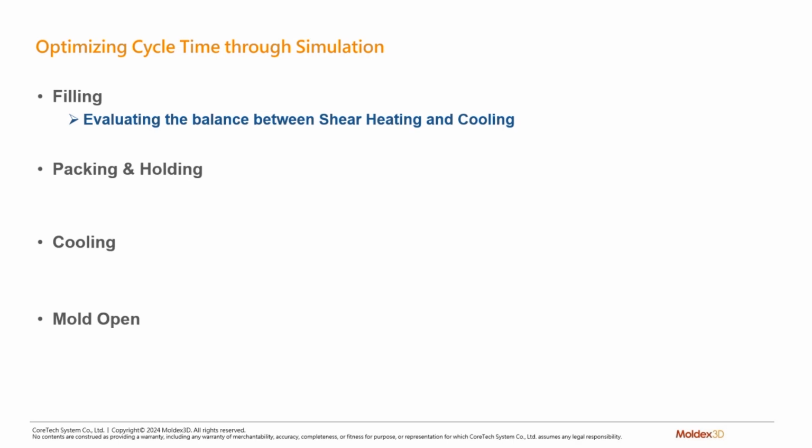So filling, how do we go? We will look at balancing shear heating and cooling, and balancing which effect dominates the flow. We will compare and understand the impact of the two and how to use that to optimize the filling time, although it is a very small portion of the total cycle nonetheless.